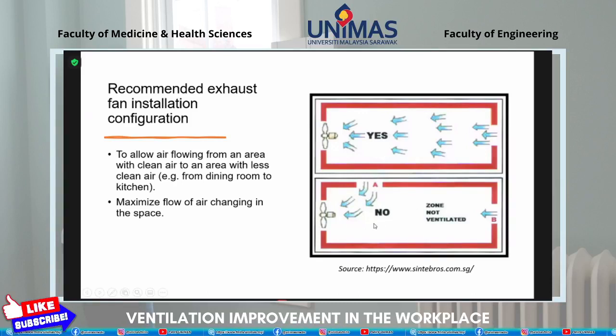While for this case, if we have an opening here, we can have an option to install the exhaust fan either here or somewhere here. Okay, two exhaust fans here, so that we have better ventilation. This air will be cleared by this exhaust fan. The air from this area will be ventilated by this exhaust fan. But for this case, if there is only one exhaust fan, highly likely there will be short circuiting from the opening of air here.